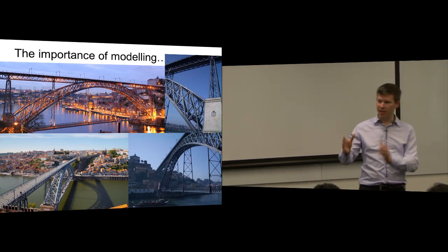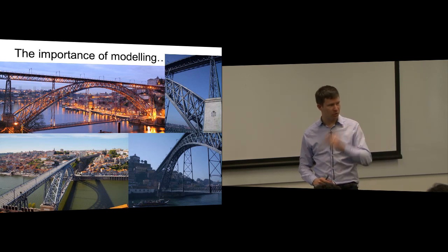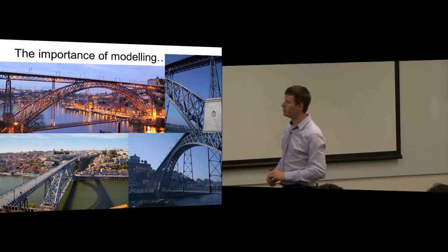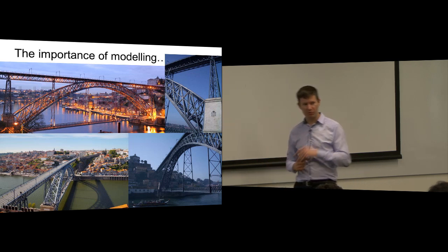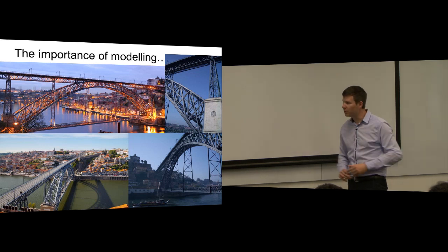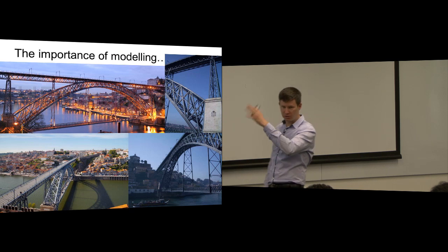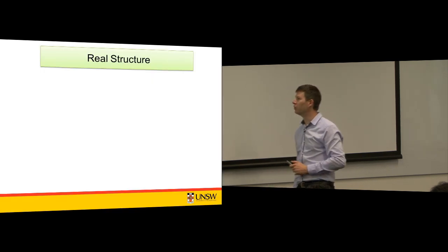I'll just throw that into ANSYS and put 2mm by 2mm by 2mm bricks everywhere, press the solve button, right? It's not the best way to solve your structure. We do need to idealize, to simplify. Where do you care about? Where's your critical piece? A structure like that is far too complicated for what we do.